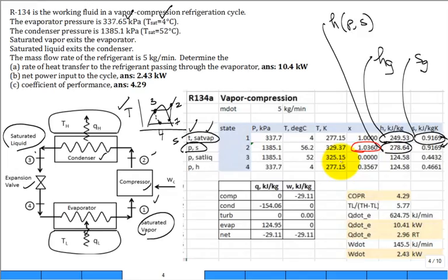Now, you can still use that to get an extrapolation of the enthalpy at state 2, but the proper way is to go to the superheated table, and if you've done this once or twice, it's like a painful memory that you have. Because this looks like I will be needing to do a double interpolation. Does that get you excited? Not at all. But unless you've done a few double interpolations in your life, then you don't know. But it's a big deal to have to do one or two of these in your lifetime. So do it if you haven't done them, or do a few more.